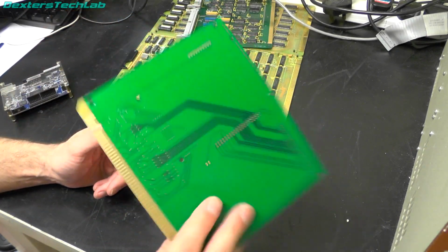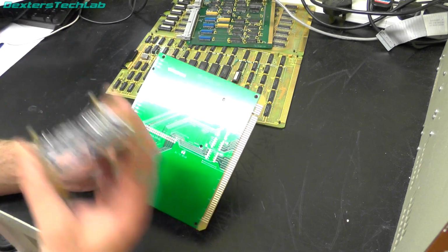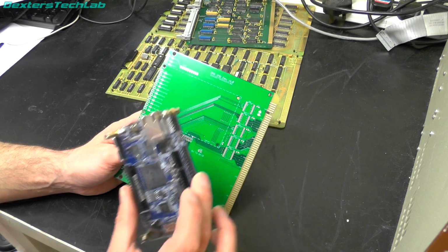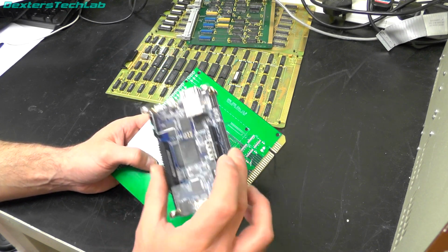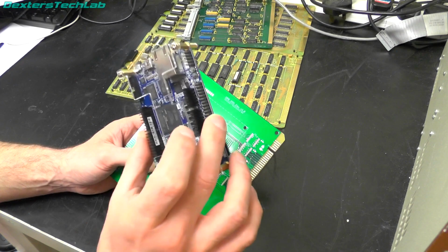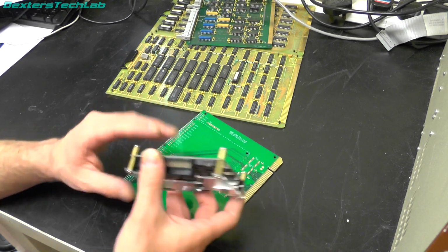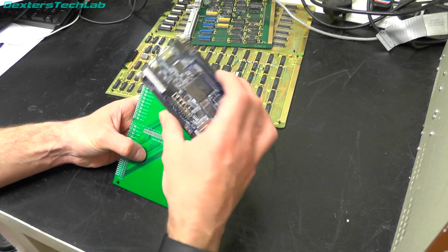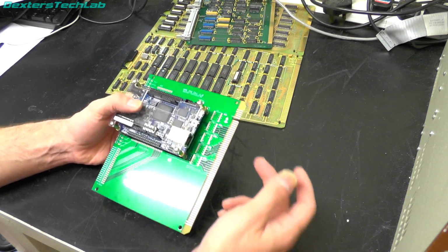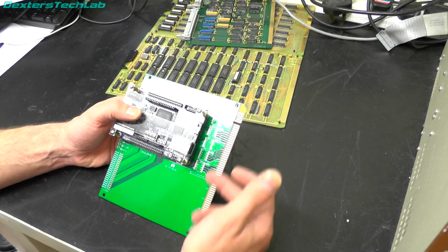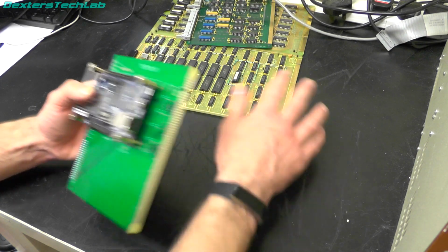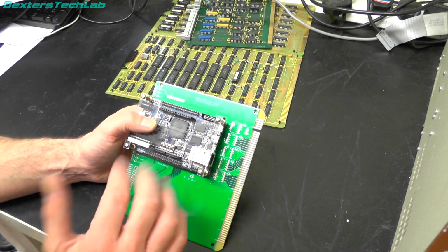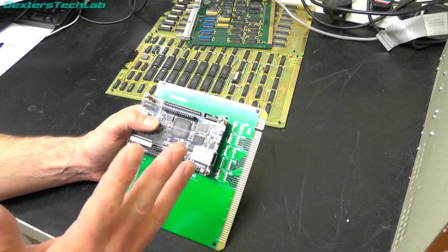So what is actually going on onto this card? Well, Ash recommended the DE10 because more than likely he's going to be doing most of the coding for this, and he's very, very familiar with the DE10 Nano. The original plan was to have this mounted on here. We'd have some buffer chips on here just to buffer between the old cards and the DE10, because there is actually an issue with the 3.3 volt signaling.